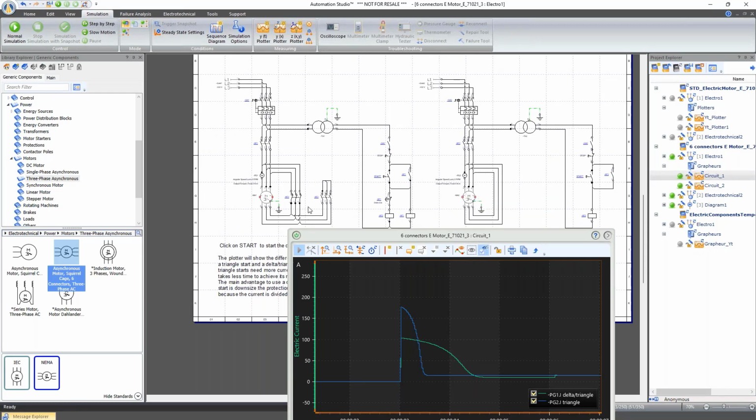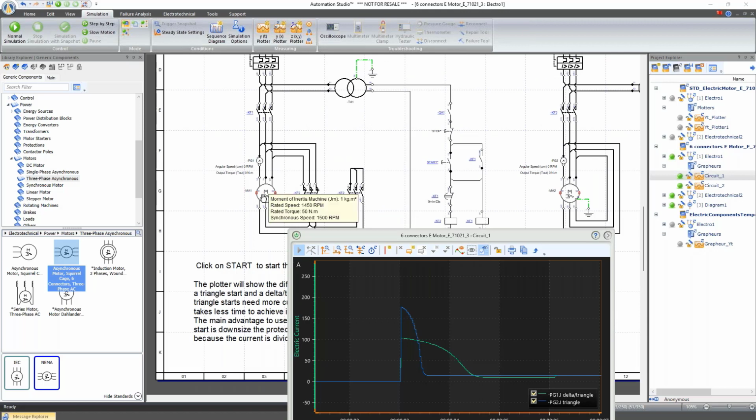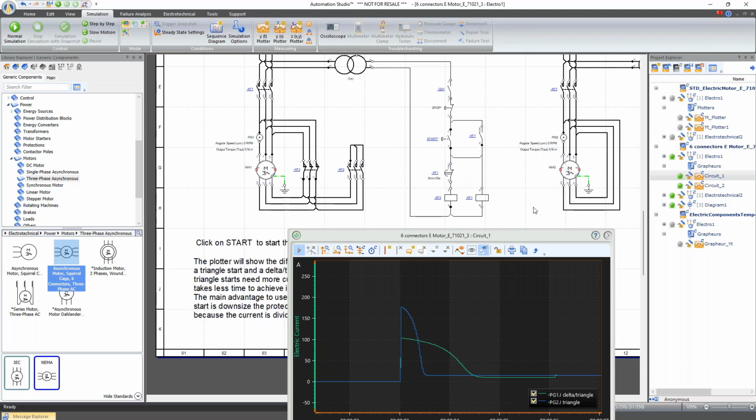The particularity of this model is that you have access to the windings of your induction machine. This allows you to have a higher voltage per winding, which means more power. But the problem is that you will obviously have a higher current. So more power, the machine will accelerate faster, but you will have a big inrush. Usually in the industry, we want to reduce this inrush current.